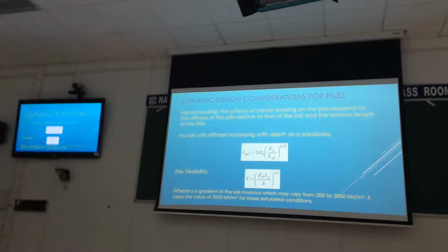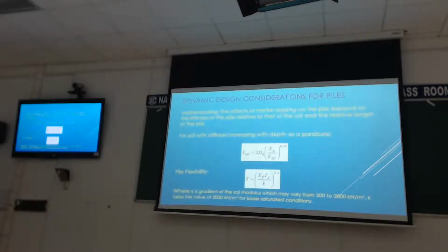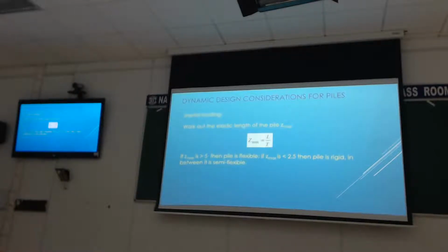The concept is that you are comparing the stiffness of the soil to the stiffness of the pile in some way. And that is right. I have no problem with that. And once you have L and T, you can work out the so-called elastic length of pile. You can say it's winding me up already. This elastic length of pile is basically to tell you how long the pile should be which interacts in the vibrations.